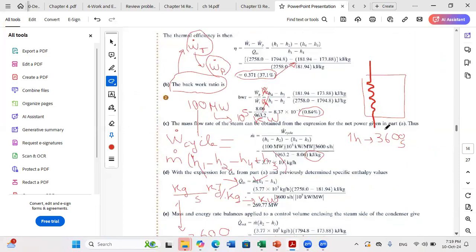Okay, so we have calculated the enthalpy, and we know all properties. So we know at the inlet of our condenser, the inlet of our condenser is state 2, and the outlet of our condenser is state 3. And we have already calculated H2. We know H2 and we know H3. That's why first, to get Q dot out, we didn't consider the whole condenser as system. We just considered as control volume, a control volume just enclosing the fluid of the basic Rankine cycle. So if we take only the fluid of the basic Rankine cycle, we can consider that it will lose heat to the outer environment.